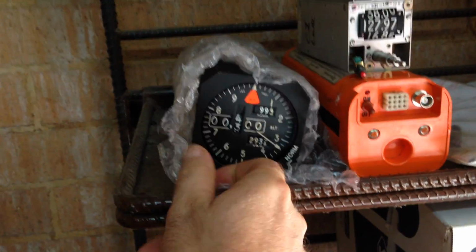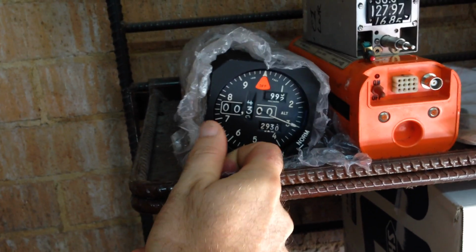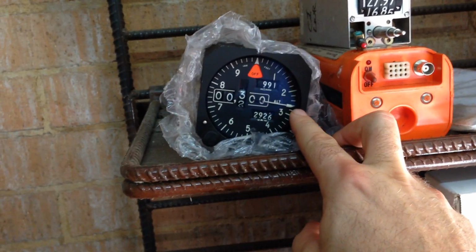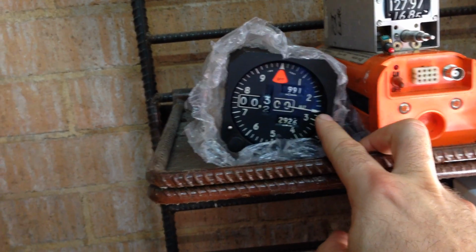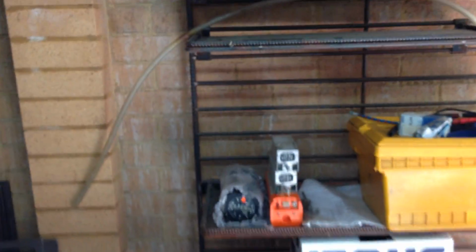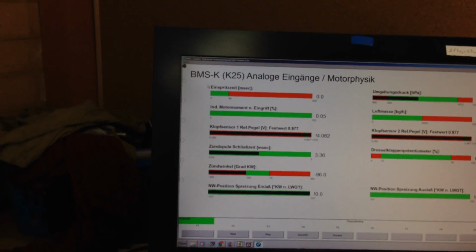Obviously I'm an aircraft mechanic, so let's set this altimeter that I took out of an airplane, which works, to 991 hectopascal, and I can see that my altitude at my house is 280 feet. So I live fairly close to the coast. I'm only at 280 feet, which is just above 100 and something meters of sea level. That's just one thing.